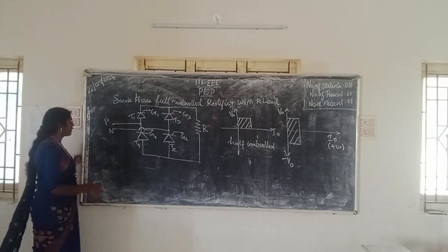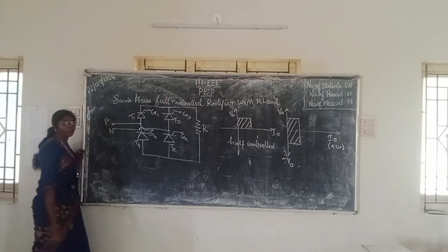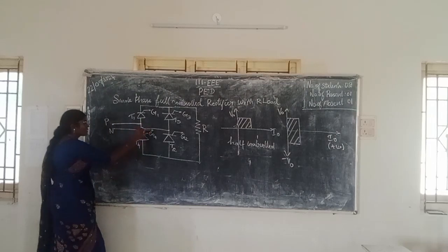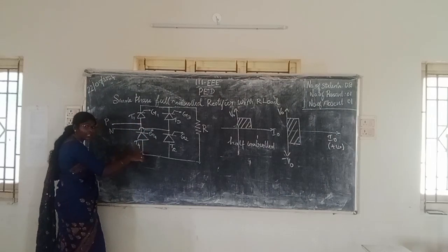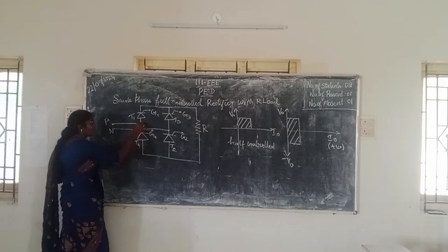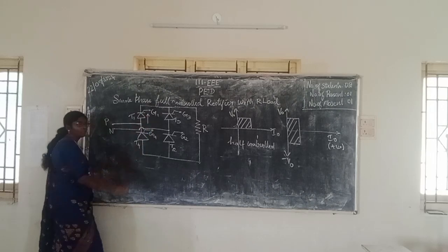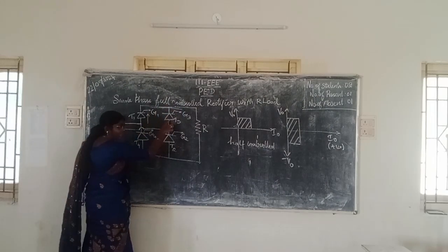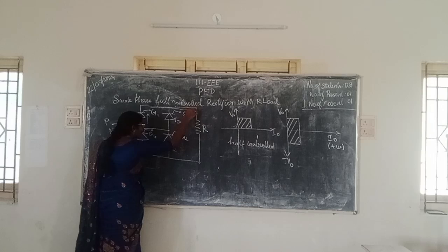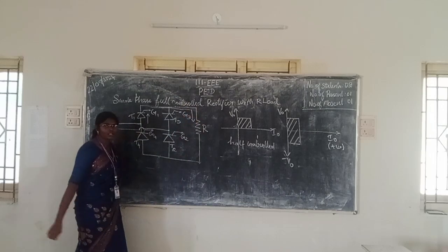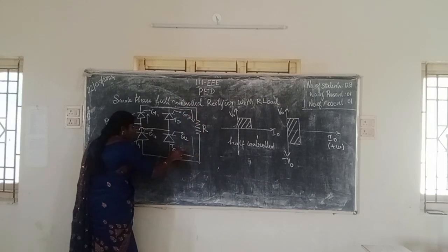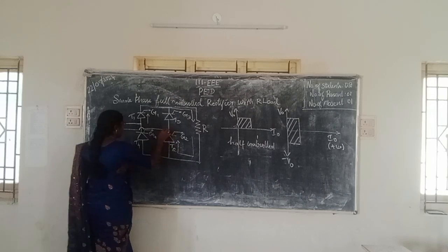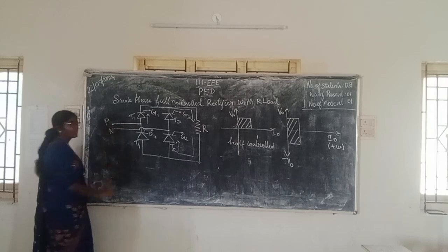So how is this happening? Look at the circuit diagram, I will tell you. Now during the positive half cycle, from phase 2, who is going to conduct here? Can this conduct? No, it is reverse, right? So who is going to conduct? T1. From T1, where does it go next? Will it conduct? No. So next it goes to the resistor. From the resistor, which will conduct? T2. From T2, the circuit will close towards neutral.